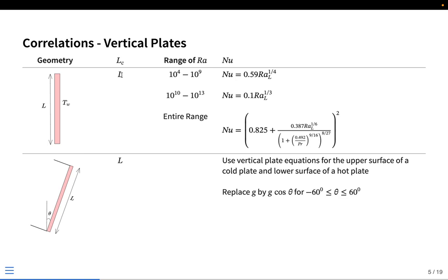For these simple geometries it might be straightforward, but when you have complicated geometries, the way to choose a characteristic length is kind of a degree of freedom. So anyone can choose a different value, so you have to be consistent and careful when using a particular correlation. In the case of a flat plate, the dimension is just the length of the plate, so it is straightforward. We do not see much of a problem. But when you have different geometries, then you have to be careful about this particular parameter.